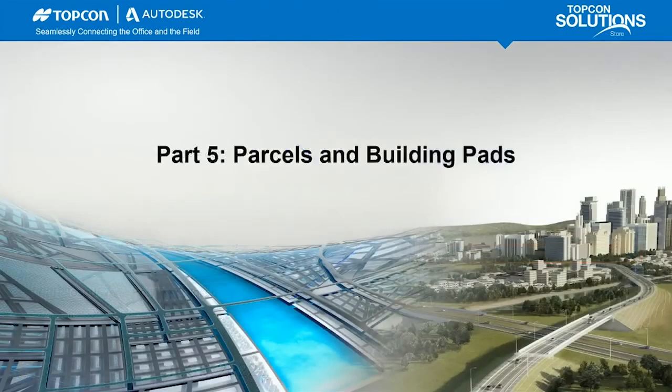Okay, part 5, parcels and building paths. Keep in mind there's no parcel grading object set when you're creating, so it'll just be a general zone for your parcel. You could name it parcels if you want to for a specific zone with specific constraints, so that you have a parcel option in your grading object browser. But just keep in mind, this is primarily just adding in a building path.